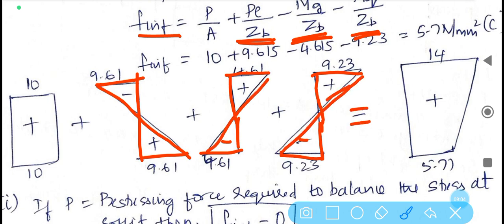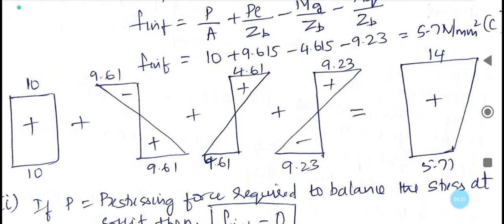And finally, the resultant stress what we have computed after taking everything into the calculation, I have drawn one reference line. The final value we have obtained is positive plus 14, therefore it is drawn to the right side. And here F inferior also it is drawn to the bottom. And this is how this stress distribution is obtained.